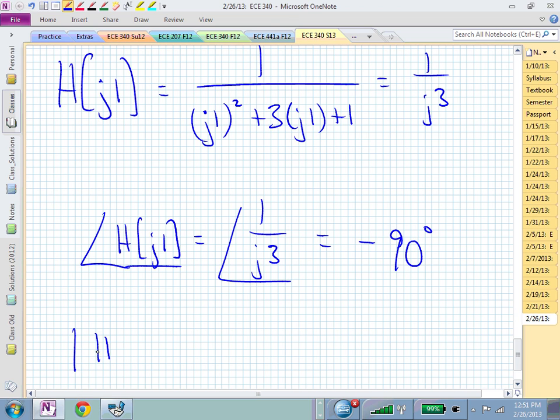What's the magnitude? I know it's pretty hard in this case. So now we take the magnitude of 1 over J3, and don't let J fool you. J has a magnitude of what? 1, doesn't it? We're just now 1 away from the origin in the S-plane when we go up J. And we've scaled that J by 1/3. The magnitude now is 1/3.